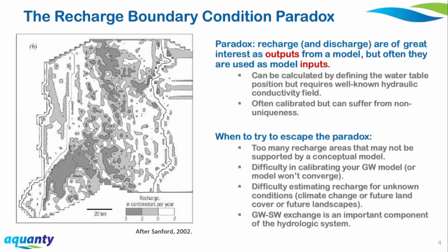So, there are a couple of caveats there. Technically, recharge can be calculated from a defined water table position, but it really requires an almost perfectly known hydraulic conductivity field, which is generally not the case. The other common method used to specify recharge in a model is to have recharge rates calibrated along with hydraulic conductivity, and that can suffer from inherent non-uniqueness.